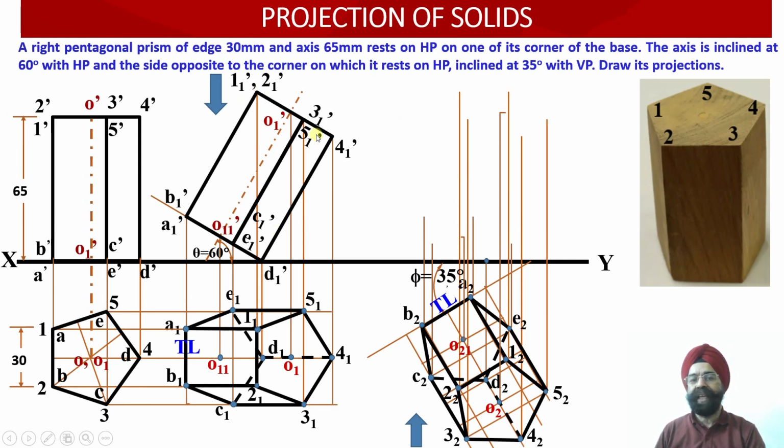And then from the elevation projection view of the previous construction, we are going to draw the horizontal projector lines. Wherever these horizontal projector lines intersect with the corresponding vertical projector lines emerging from the same points, we will be obtaining the corresponding points of the elevation projection view of the oblique solid. So let us start with this.